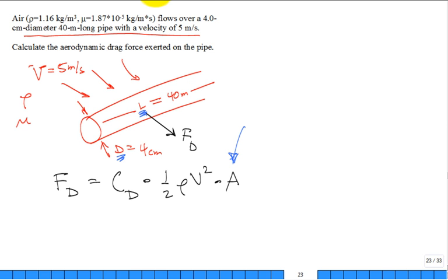So having graded a number of exams over the years, I'll see that the area is given to me as pi d squared over 4 times L. It's a pi dl, or without a pi, just a dl. One of those answers is correct. Or even somebody will put 2 pi dl or something. Anything with a pi in it is incorrect. The silhouette area of a cylinder is just the height, that is the diameter, times the length. This is correct. True? So there you go.